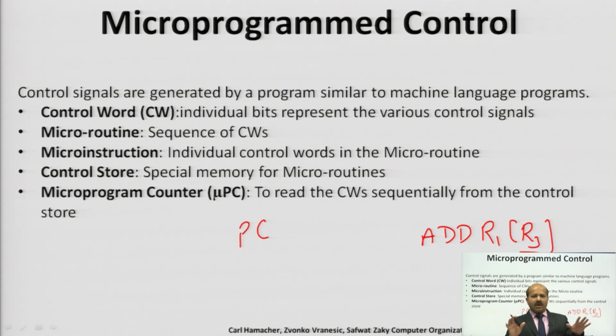There were 7 control steps we have seen, and different commands like PC out, Z in, MAR in, MDR out, and R1 out, R1 in, different types of control signals we have seen in different steps. So, what should be the proper sequence of these signals and when are these signals to be issued?